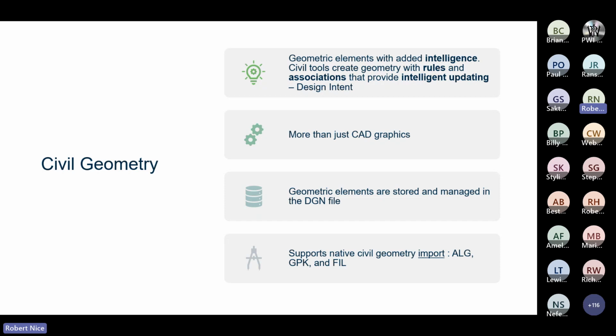So this design intent as well carries through the product. So as a simple example, I've got my main line. Maybe I've offset something, a piece of geometry, 3 meters off to the left. Simple as that. It's just an offset, partial offset. So a zone is 200 meters long, 3 meters off to the left.